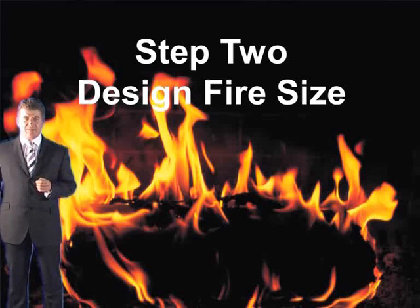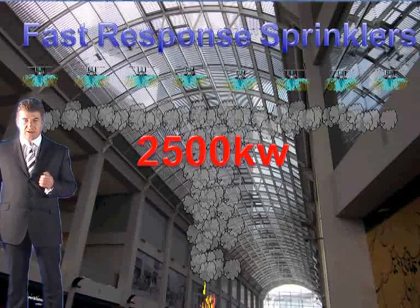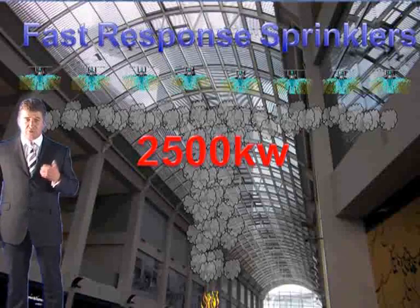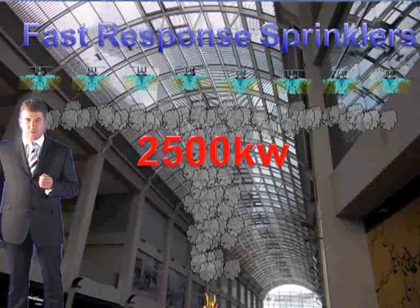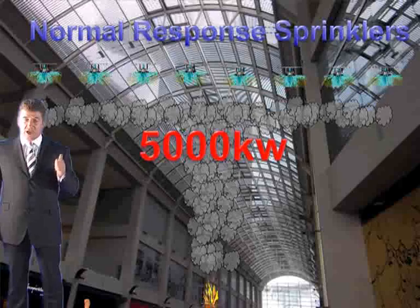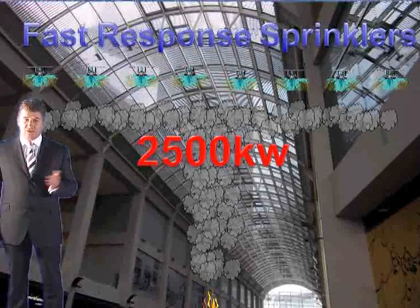Step 2, your design fire size. Now, we're told that these are fast response sprinkler heads that are going to be put in the building. So it's the convention, if it's fast response, to assume that the largest fire size is going to be 2,500 kilowatts. Now, don't forget, if there'd been normal response sprinklers, then the design fire size would have been 5,000 kilowatts, but these are fast, so it's 2,500 kilowatts.